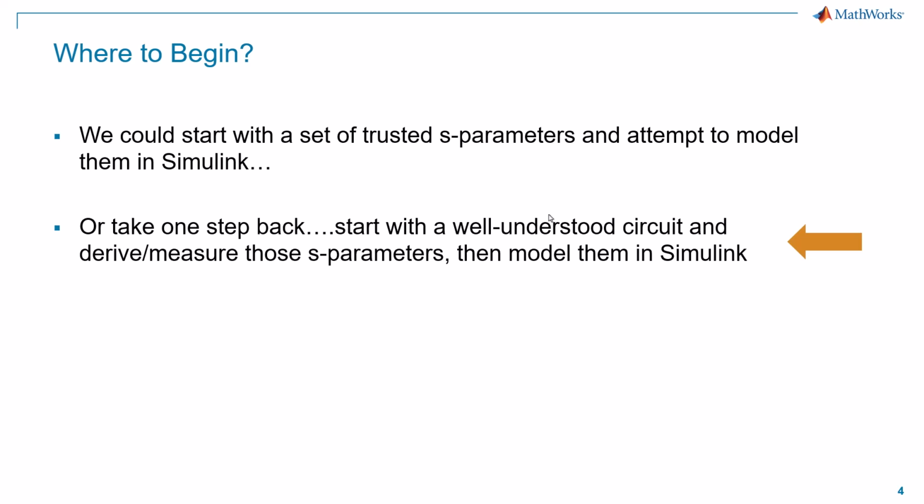So where do we start this exercise? Well, anytime you're starting to test out a new methodology, you want to start with a trusted set of data. And so one option would be to take a trusted set of S-parameters you have and attempt to model those back in Simulink so that when you're done, you know what the right answer is. You know that the model is matching the data.